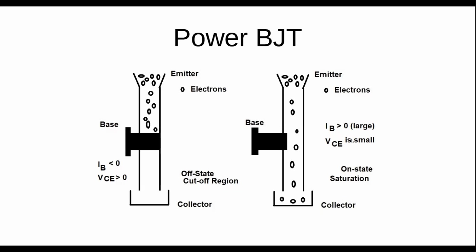And every time we have resistance, it means that you're going to have power dissipation. So the idea is that you have to have a heat sink, especially when you're dealing with these power devices. You need a heat sink to keep this device cool, to draw away the heat from the device.